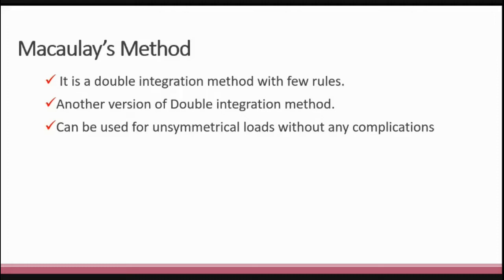So this can be used for unsymmetrical loading cases, eccentric loading, or 2 or 3 loads, and you can solve them using Macaulay's method without any complications.